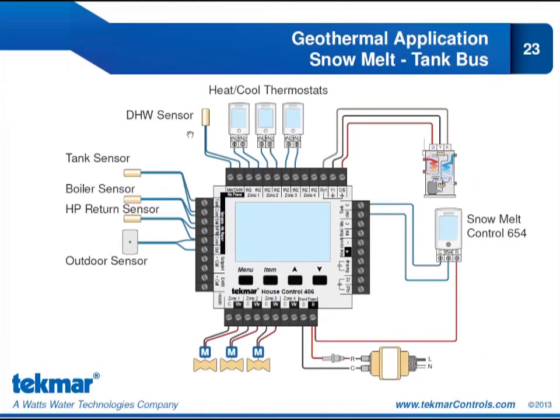For my sensors, I have a domestic hot water sensor, a tank sensor, a boiler sensor, a heat pump return sensor, and an outdoor sensor. So here I'm able to use the domestic hot water sensor because I don't have a mix bus, so I don't need a mix sensor, so I can use the shared terminal input for a domestic hot water sensor.